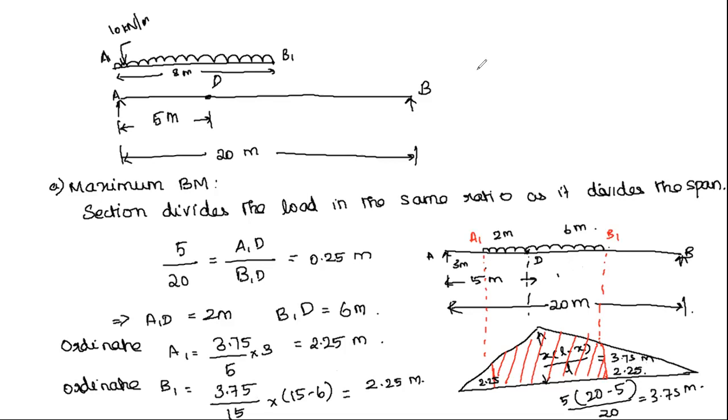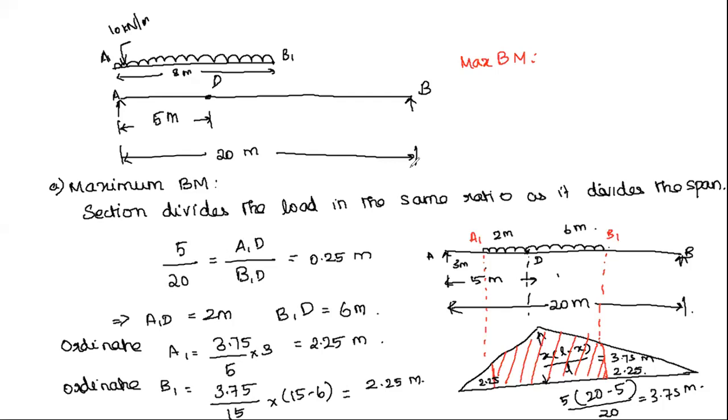So now the maximum bending moment. So what will be the maximum bending moment? Load intensity into area of the ILD under the load.